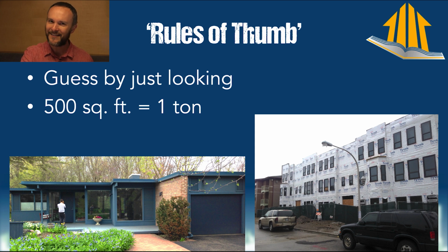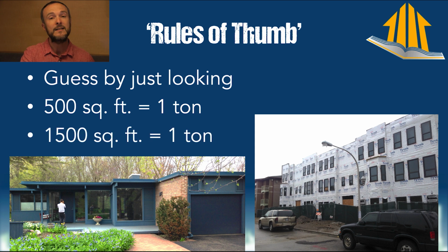So let's take that seriously. There are reasons to oversize, for reasons that I'll get to in a few minutes. But nowadays, if there is such a thing as a rule of thumb, which there's not, so don't believe this, but if you're building a house that's going to be relatively high performance, meaning it's going to be meeting energy codes, if you are in a state that has energy codes, then you're looking at something like 1,500 square feet per ton. So if you used to have a 1,500 square foot house, you'd have a 3-ton air conditioner. Nowadays, you would have a 1-ton air conditioner. They don't even sell 1-ton air conditioners sometimes. So you want to be able to understand all that.